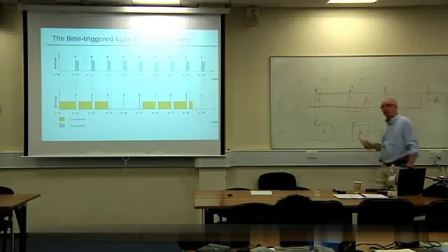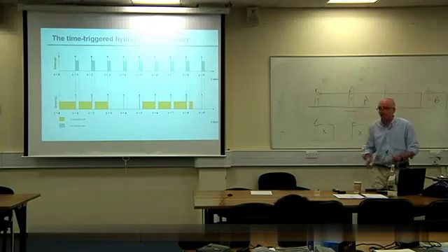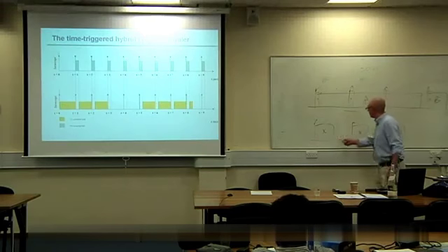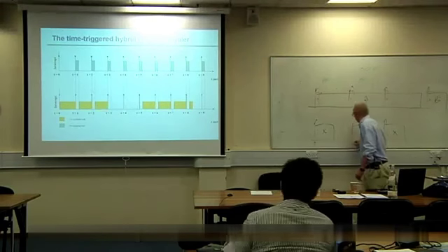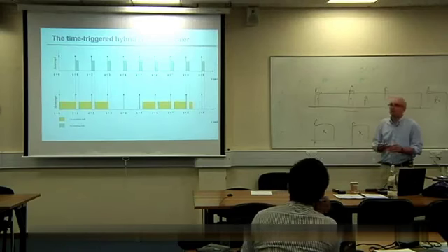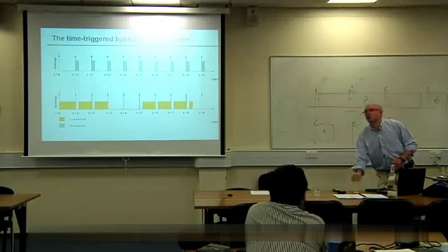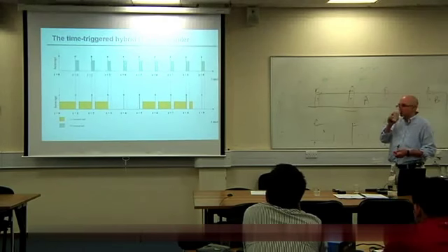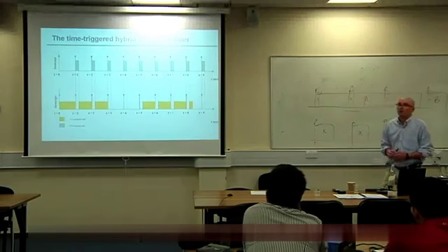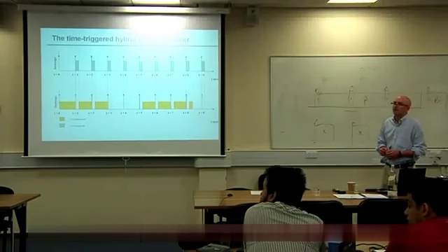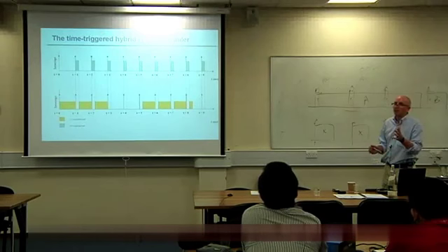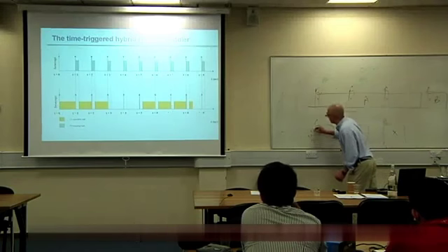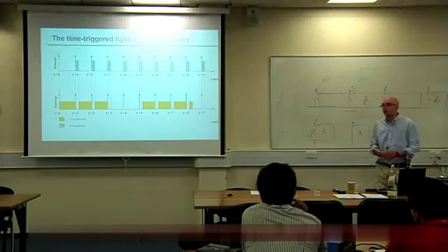We'd expect very low levels of jitter. Why? Run it at that time every single time. Okay, and what state is the processor in here, here, and here? In our typical TTC design that we've used up until now, the task count is at 0. You're at a known state where you're guaranteed that that's what it's waiting for. So what state is that? I think idle. Okay, and that's the key bit. So we're in idle mode each time.